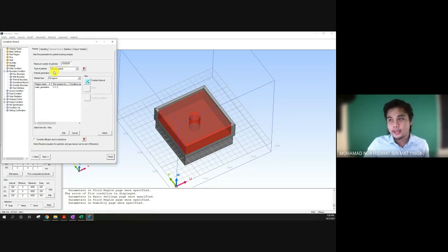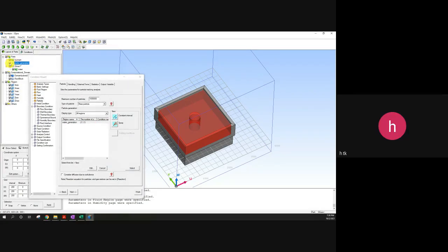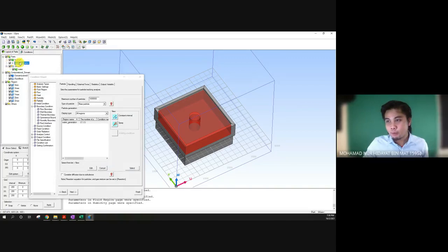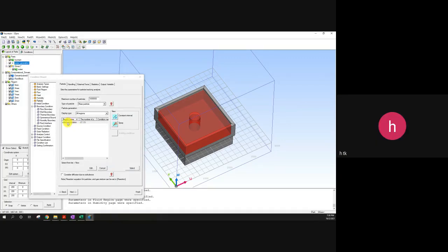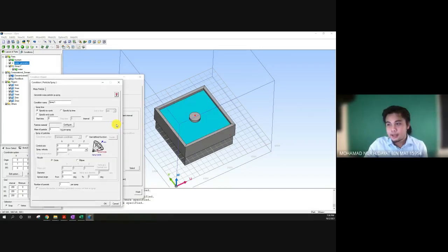The type of your particle, of course, water has mass, right? So assign it as the mass particle. After you assign the mass particle, click here, water generation. Since we created the point, remember? This is our point. We named our point water generation, so it appears here. This is water generation at 111, XYZ, and then click spray. I want to make it a spray. So click spray, and then you can see the water fountain having the angle of spray.